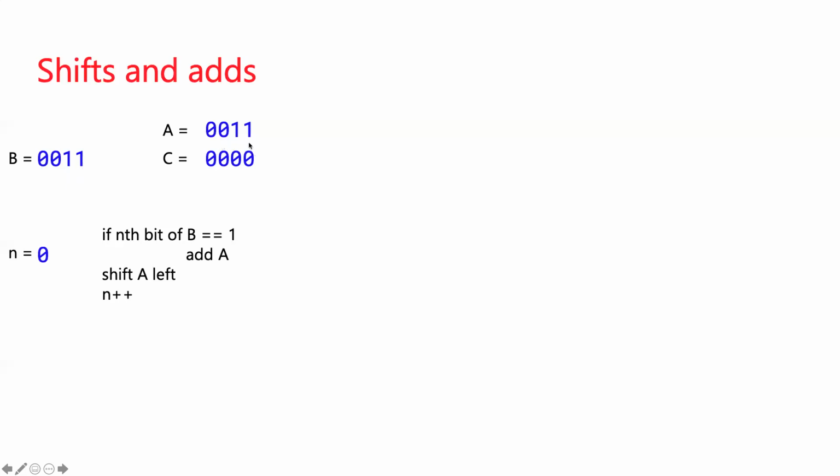But in every iteration of this operation, we're going to shift it to the left. So initially, and this down here is pseudocode for what the microcode might do. So I won't point to this a whole lot, but as I'm talking through this, I'm doing what this little program says. So first we look at the low order bit of B.